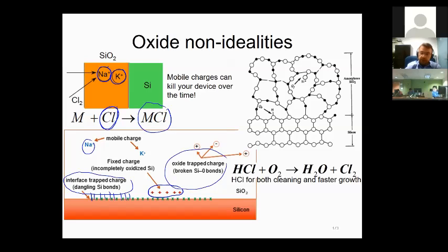The whole issue is like an architectural issue. You're trying to build an amorphous layer on a crystalline structure. So as you can see, some of the dangling bonds will not be compensated, so they will bring you these interface charges. That's going to be a recombination site. If we're talking about the diode performance, that's going to be a defect portion for our oxide.